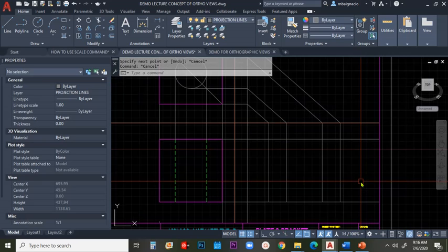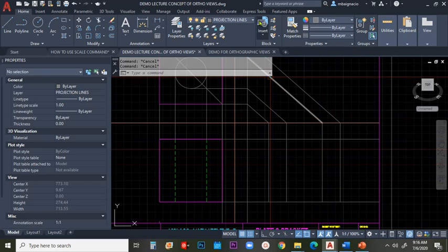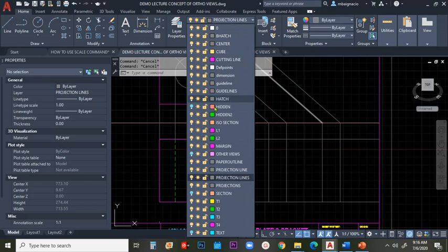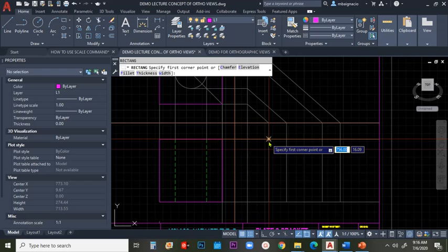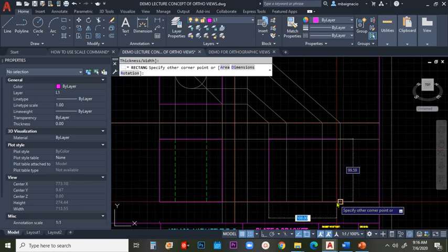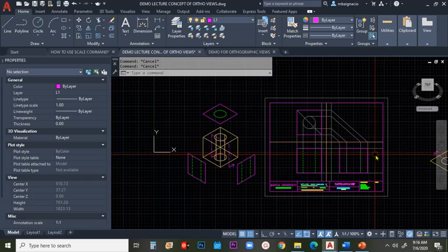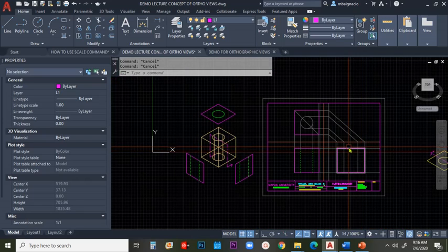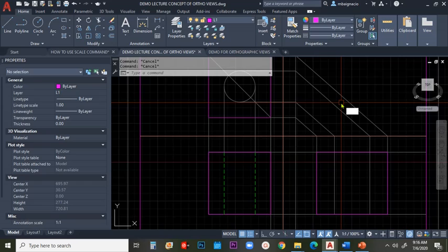Now, since you already have the boundaries of the area here, I'll just go here on L1 and then create a rectangle, and then I'll connect each point from top left going to lower right, and then I'll trim this down, TR.